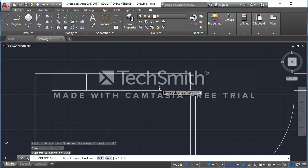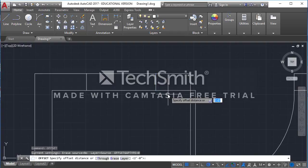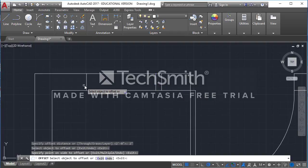A typical window mullion is anywhere from 1, 2, sometimes 3, 4 inches. I'm just going to make it 2 inches. Whoops, that's 2 feet, sorry. So offset, enter, I'm going to type in 2 inches, and that's going to be my window frame.